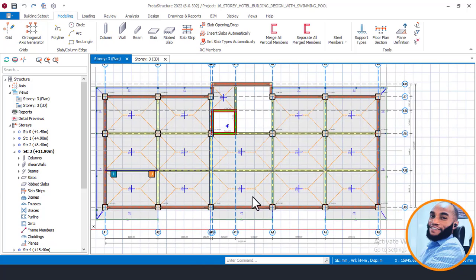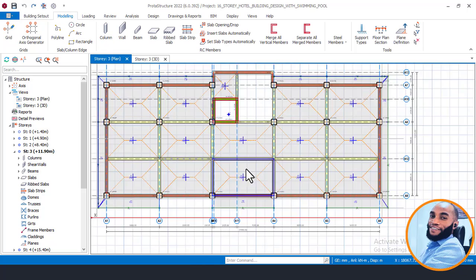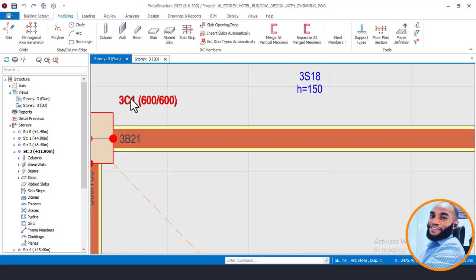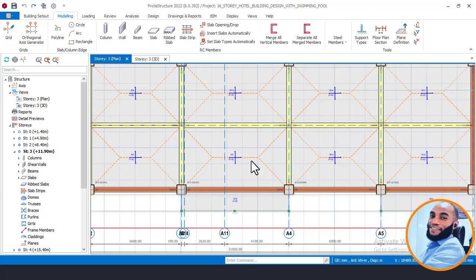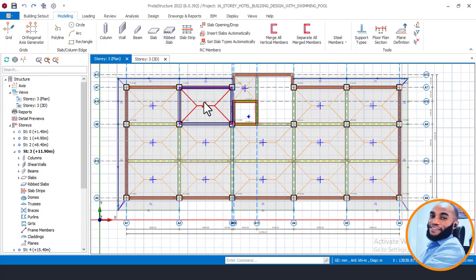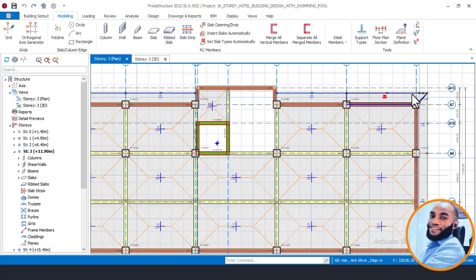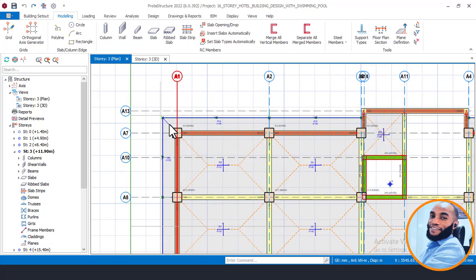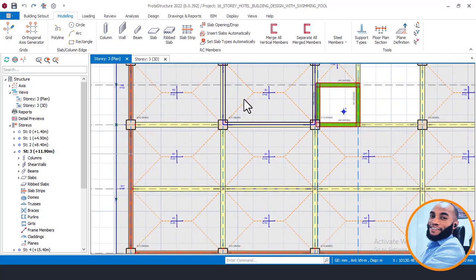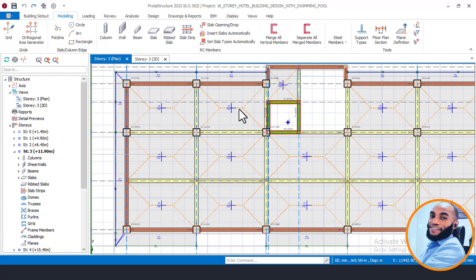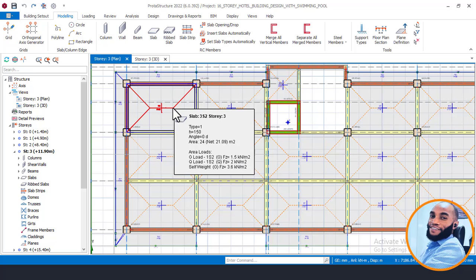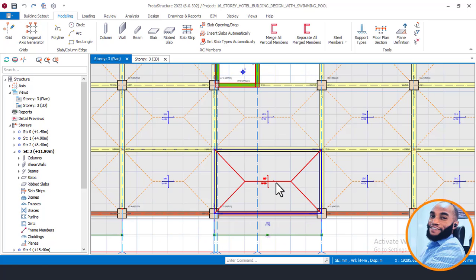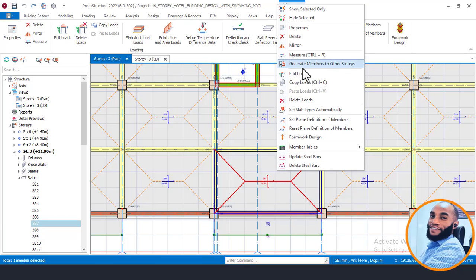So right now you can see that this is the point where we are going to start, which is the 3rd floor. On this, I'll have to remove all the solid slab around this place, but I will leave all my solid slab at the edge of the cantilevers, because I want to still maintain my cantilever slab as a solid slab. So I'll only remove the solid slab found in between these partitions. First of all, let me remove this first. I'll come here, delete slab.